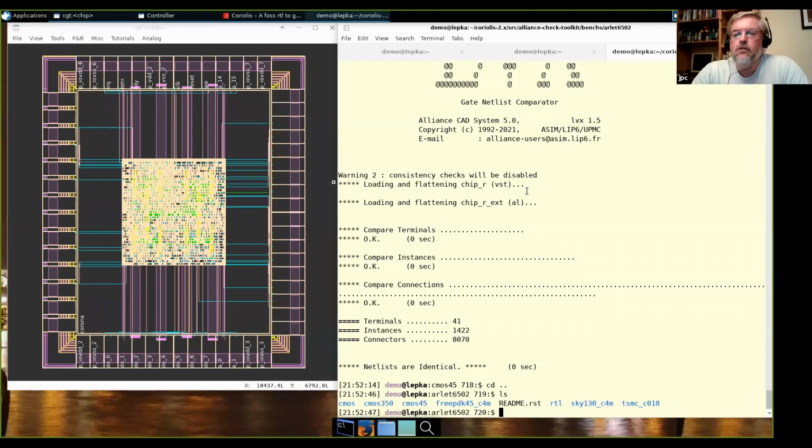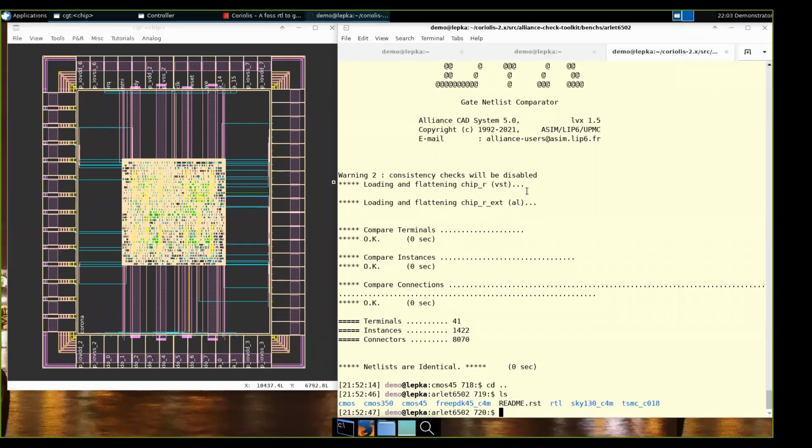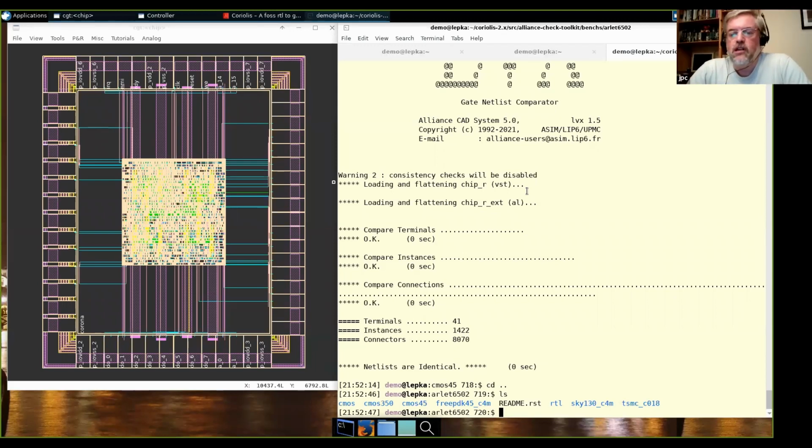It's just a uniform way. The only difference is you'd have to add some extra rules, wouldn't you, to make sure the analog is, for example, cleaner than digital in some areas. Yes, of course. It's not routed like digital, but it works. The global routing structure can support analog design, and the detailed router can support analog parts with specific rules. For example, symmetry. You can add a symmetry constraint inside the router and tell it, okay, this wire and this one must be fully symmetric, and so on.